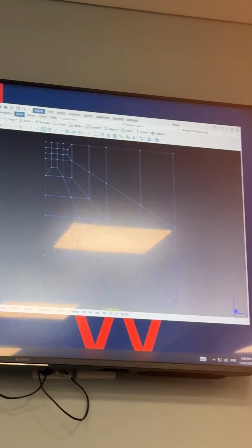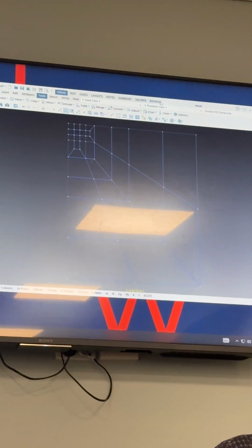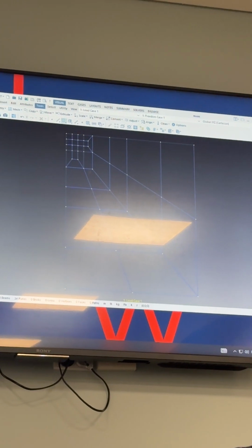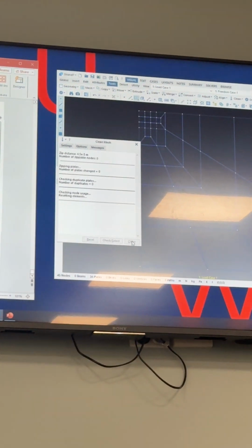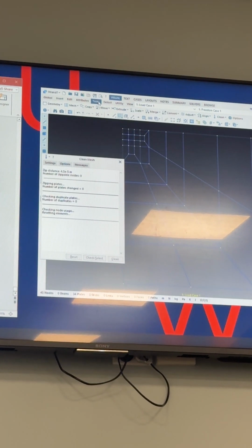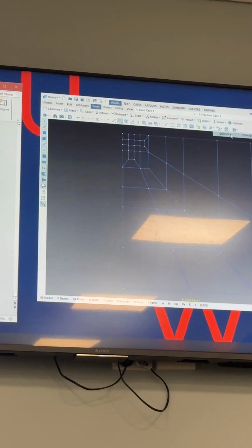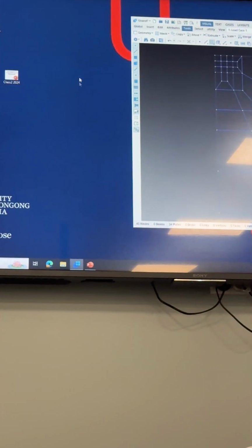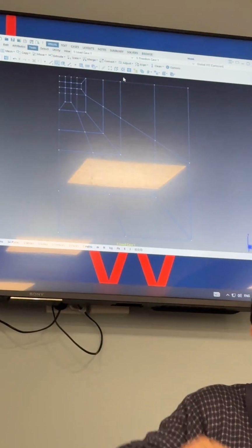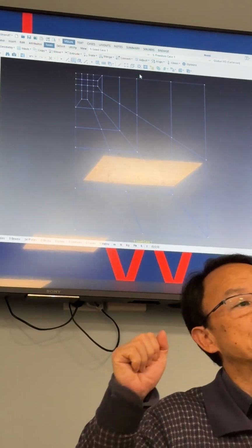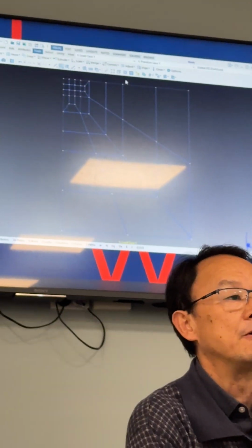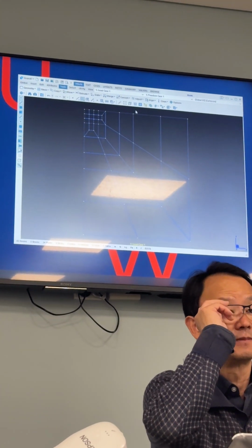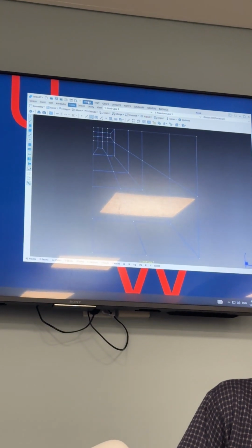How to check it? Visual, tool, clean. You clean the mesh. And then visual, tool, clean, geometry. And there are some other checks as well. After you finish the FEM geometry model and check it, you're going to import the boundary condition. The boundary condition will start now.